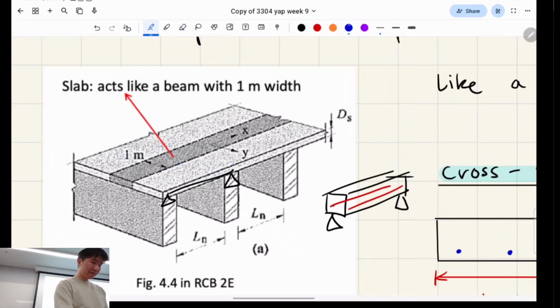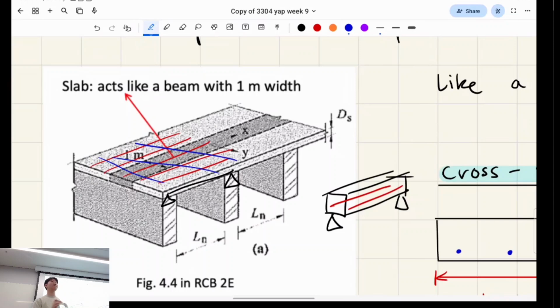Anyway, so we were talking about this direction being the axial direction, and that's the direction of our primary tensile rebar. So why do you reckon we have rebar facing the other way for a slab? For any slab, you actually want some secondary rebar, just so it doesn't break one way. That's right.